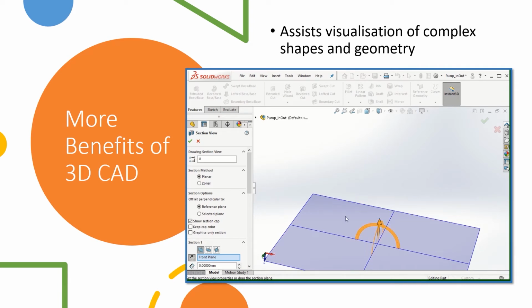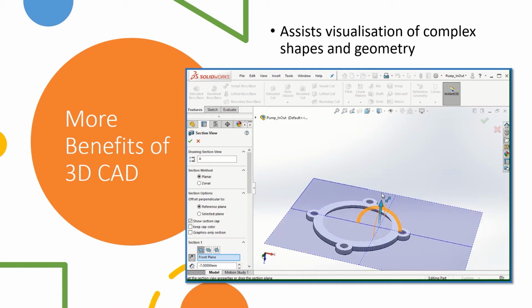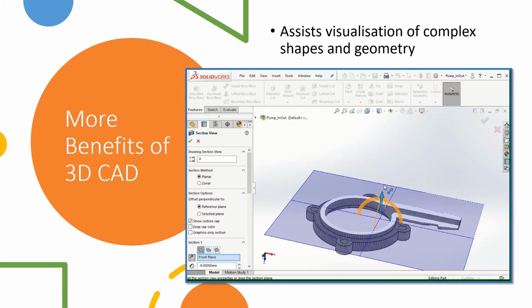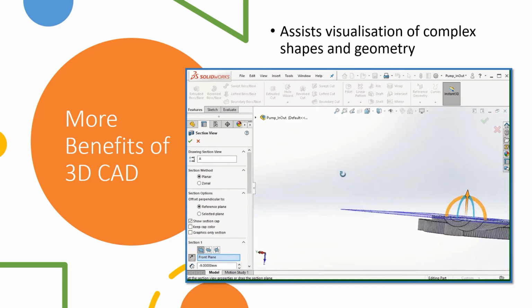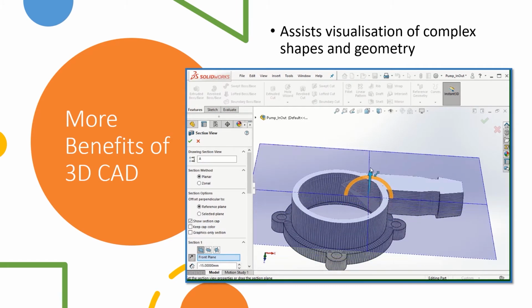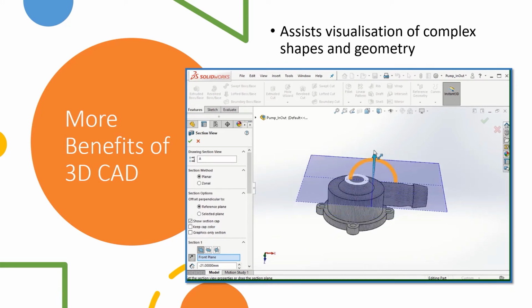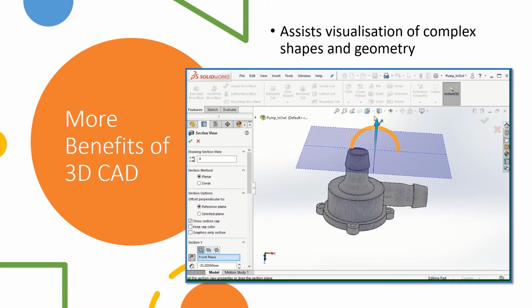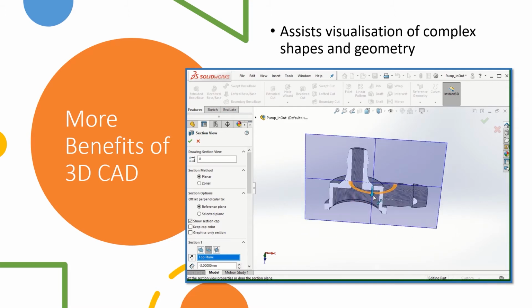And I'm going to use this cut plane, so we're currently looking at this front plane. If I pull this front plane up, we'll start cutting into the part, and we can then inspect any of those elements as the part is having this cut section applied to it. So that's a really big benefit of 3D CAD, and I can change that cut plane into different orientations. I can have a look at all these different edges.